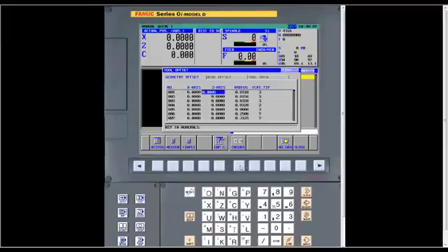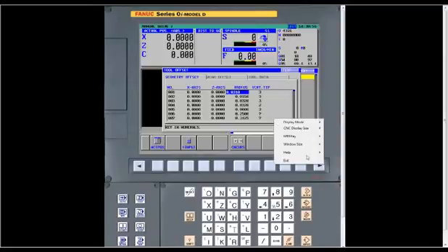Now we'll change the cursor as we page over. The next value that we need to fill out is the radius. What that's asking for on a turning tool is the radius of the actual insert. I know on my tool, this is an 80-degree left turning insert, and I'm using a 31 thousandths nose radius tool. And where I get that number from, let's do this.